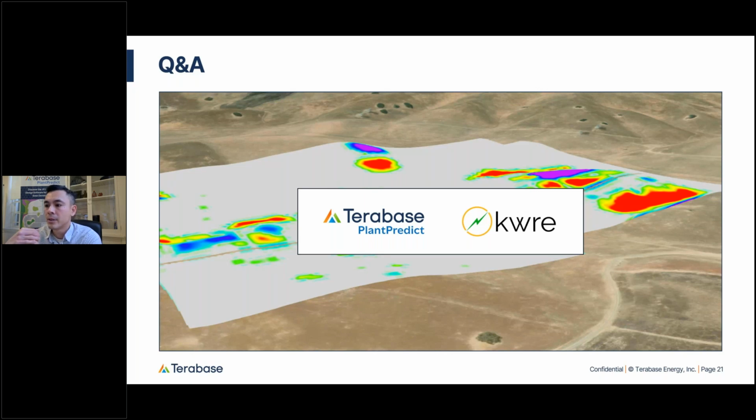It's really about the terrain data you have. So contour lines is the format we're intaking. It's quite efficient, but it does vary from site to site depending on the resolution and the density of the contours you have in your project. And again, as Andrew mentioned, you can decide on a very fine contour resolution, so that does affect how large your file size becomes.